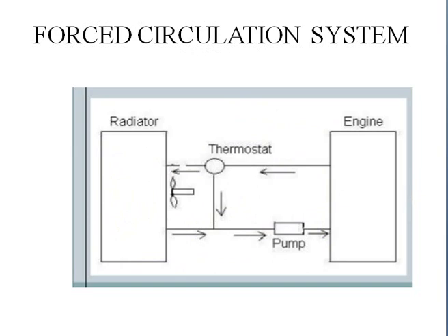This is a forced circulation system. Just what I have explained in the liquid cooling system, the same concept is here. This is the engine, this is the radiator. Once the coolant, it means the water which is present, reaches a particular temperature, the thermostat valve will sense that and open. As a result, the water present in the engine will go to the radiator, and once the water gets cooled, the same water will be repumped to the engine.